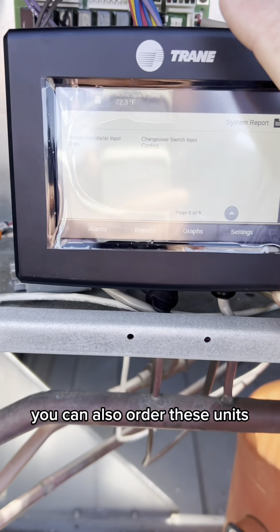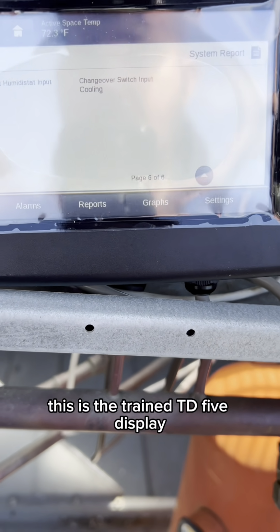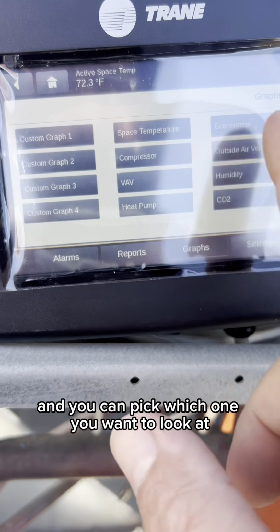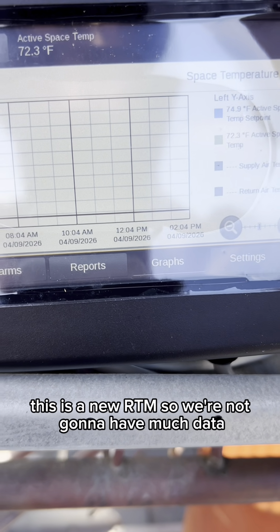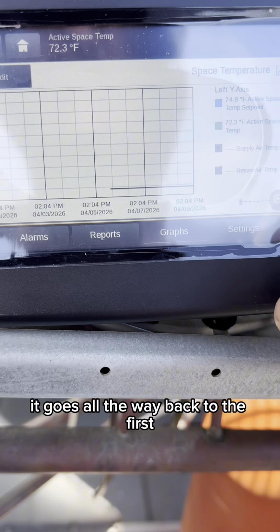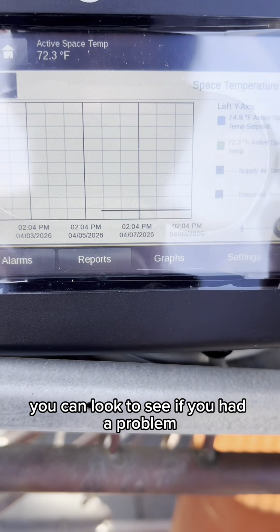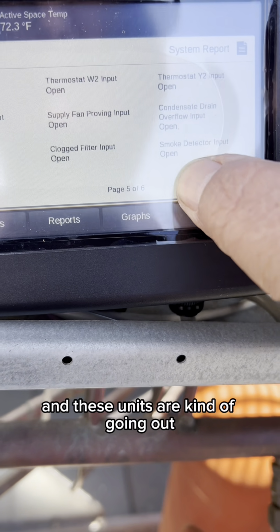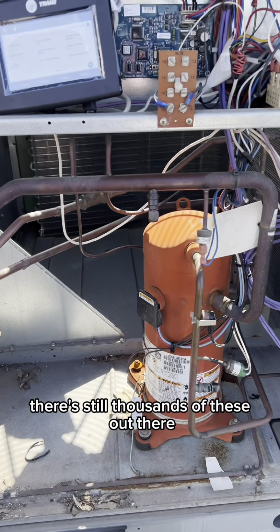You can also order these units, they'll come mounted in the machine like this. This is the Trane TD5 display. And it also has graphs here, and you can pick which one you want to look at. Right now, like I said, if we look at space temp, I only just plugged it in. This is a new RTRM, so we're not going to have much data. So it's got some time. It goes all the way back to the 1st, so at least a week's worth of data. You can look to see if you had a problem, if you had any spikes, any troughs, anything like that. Again, these units are kind of going out. They're aging out. There's still thousands of these out there.